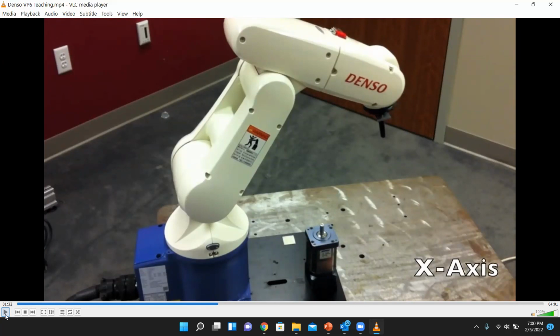In XY mode, you are giving the commands to the endpoint to move forward, backward, left, right, up, down, like that. It is the Cartesian space command. In order for this command to be executed, the controller has to control all these joints, combining the individual motions of these joints in order to move this point linearly in the workspace.